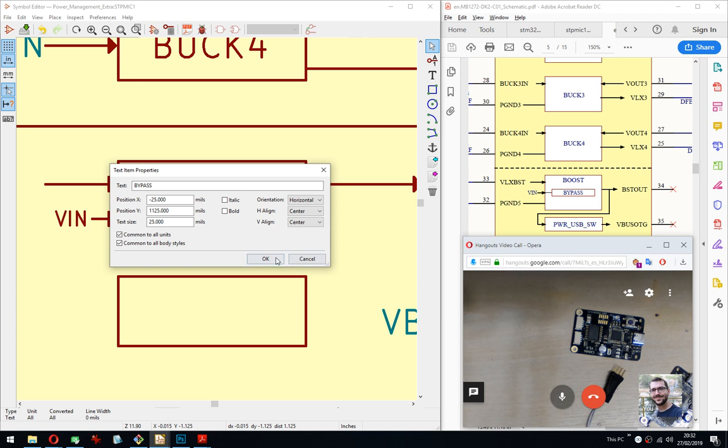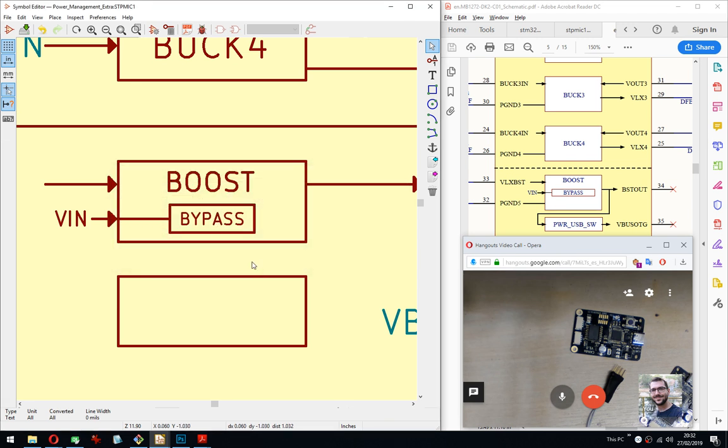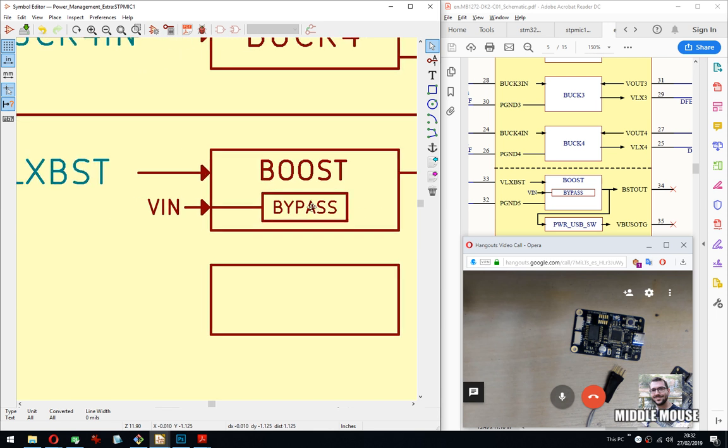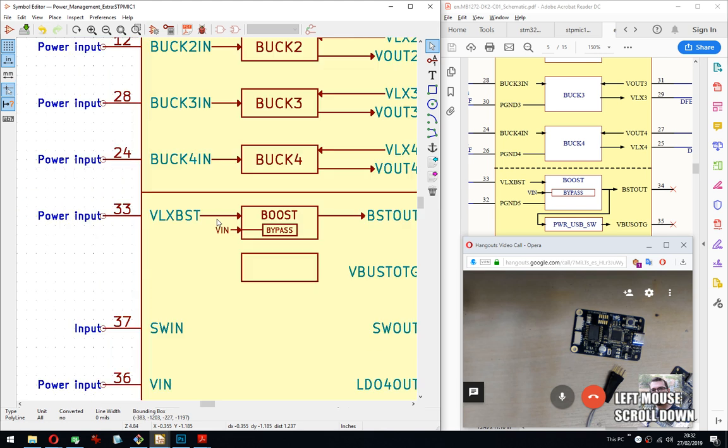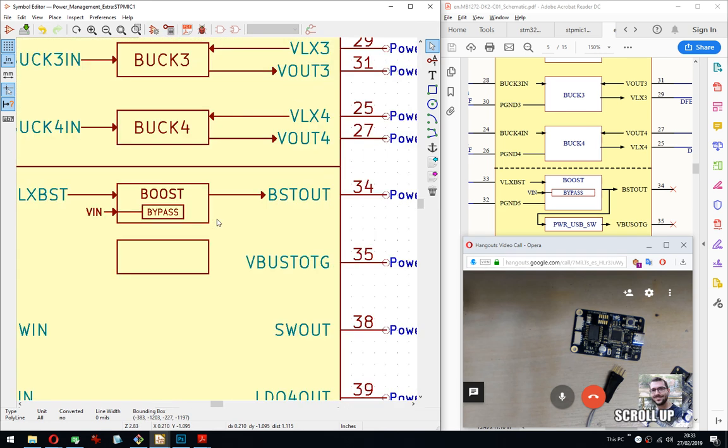Especially the Type-C socket you found. It's a really good thing because it has through-hole legs, so it's really robust. It doesn't just lay on the soldering and rely on the solderer to keep it in place. It actually has stems that keep it in place, and that's pretty important for something that's going to be plugged in and out a lot of times.